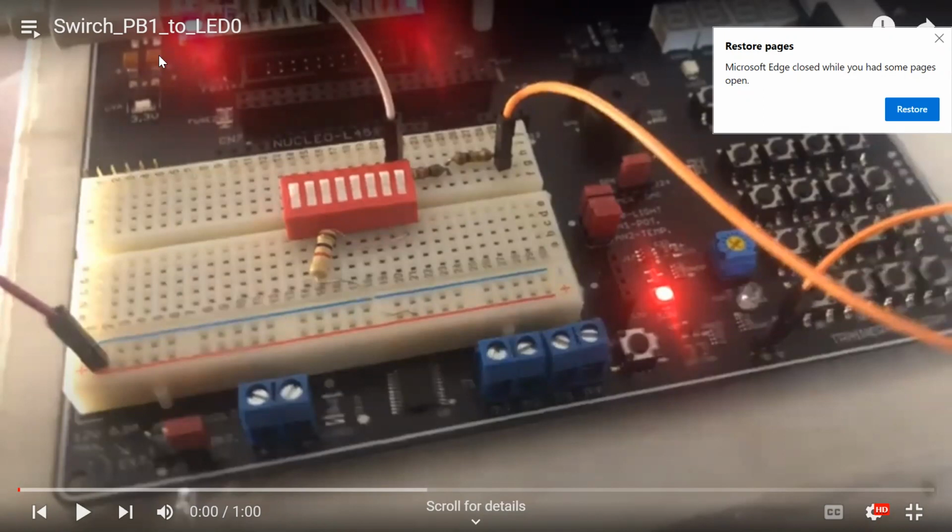But anyway, ground is here. So you need to connect one terminal of the switch to the resistance to 5 volt. I'm using only one switch. The other terminal is connected to the resistor, the resistance. You don't need to make a series this way. I made it in series because I didn't have the resistor value I need, right? So I got 2 and made it in series. Anyway, then I connected this one to the ground. And then this one here should be connected to the microcontroller, okay?